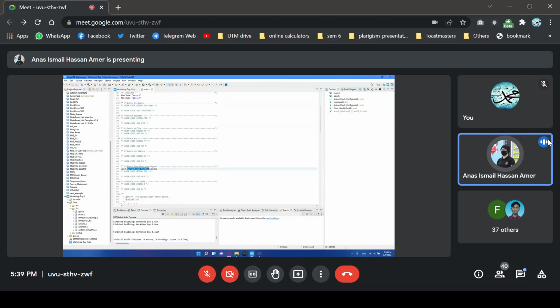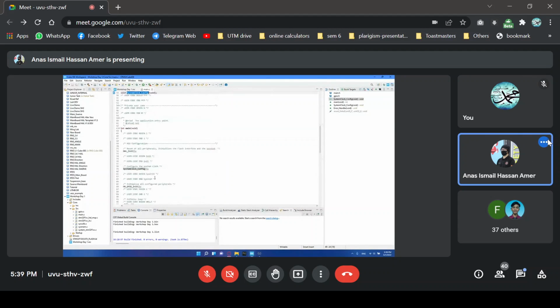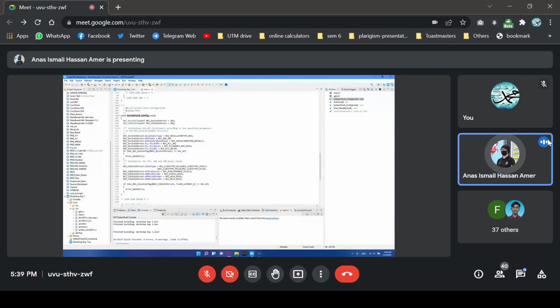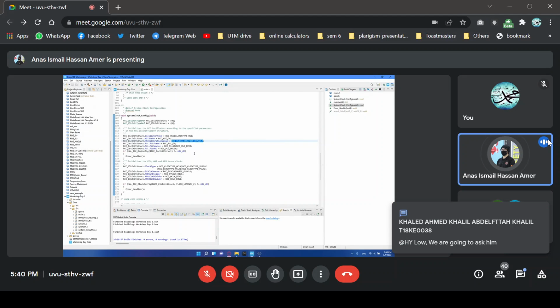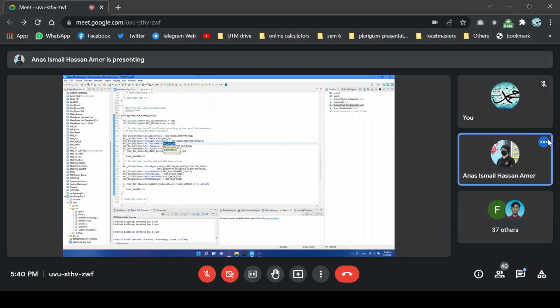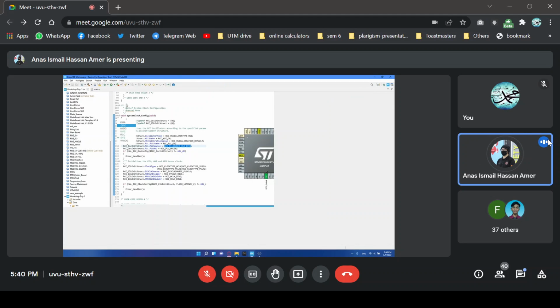You can see this is the system clock config. We found it slightly down. So these are the clock options that we chose just now. We're using the internal oscillator, HSI. It's on. Calibration is the default calibration. We didn't change anything. And then we're using the PLL clock. So PLL is on. The HSI is divided by 2, as you can see.